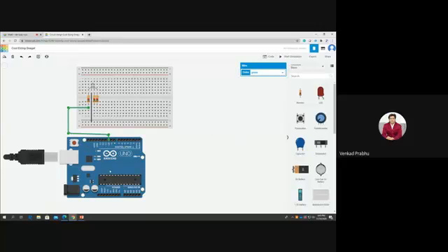If you look at this, the Arduino has two sides with pin slots. On the bottom side you can see the power pins, ground, 5 voltage and 3.3 voltage, and input, output and reset pin options. The analog pins are here, A0 up to A5, and on this side we have digital pins with pulse width modulation, which is PWM. This is a huge concept which I cannot fully address within this time limit, but to the maximum level I can, I will deliver it to you. I will explain it along the flow.